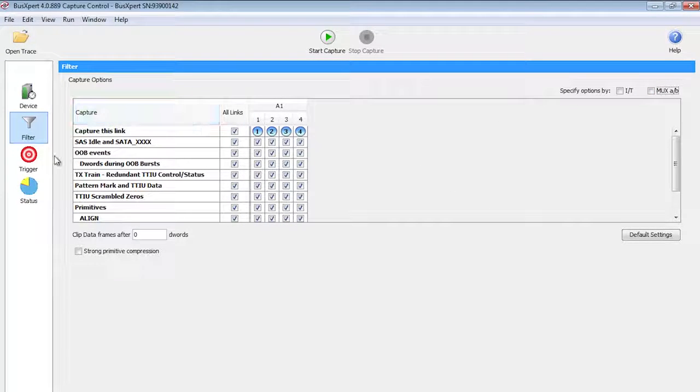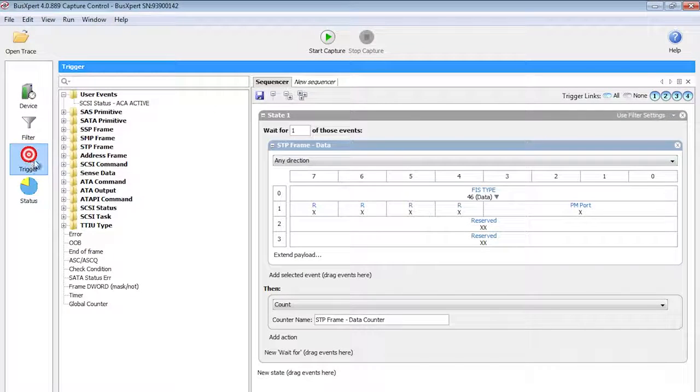Moving on to the next area, trigger condition. Triggers allow me to control what I am looking for. That ties back to my buffer capture routine: what condition am I looking for, do I count and save into the buffer that I am looking for, the anomalous condition.